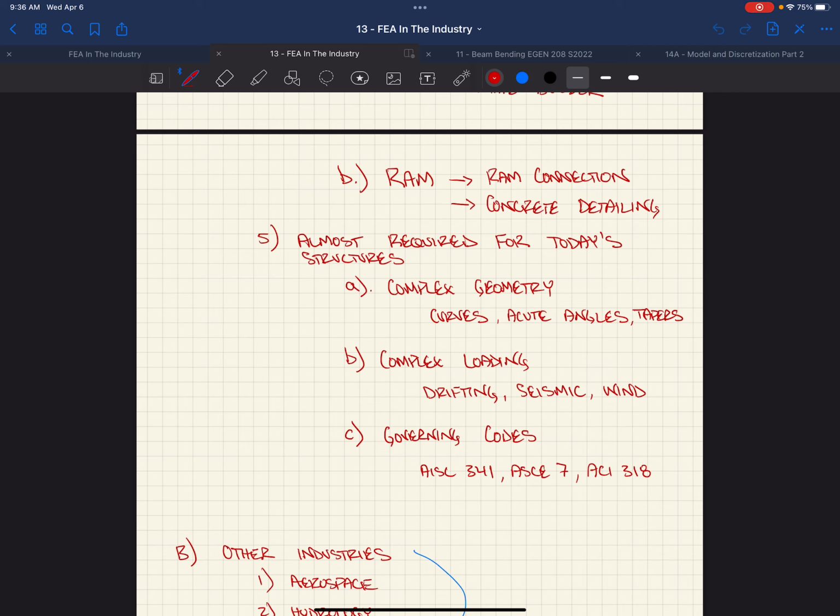They changed the seismic compactness requirements for braces, which, have you guys dealt with those yet? It's kind of nice, in the seismic manual, it gives you this nice little table, right, Sutton, that tells you, you can select which brace, maybe gives you a little dot. And it's mindless work. Nobody checks unless something bad happens, right?